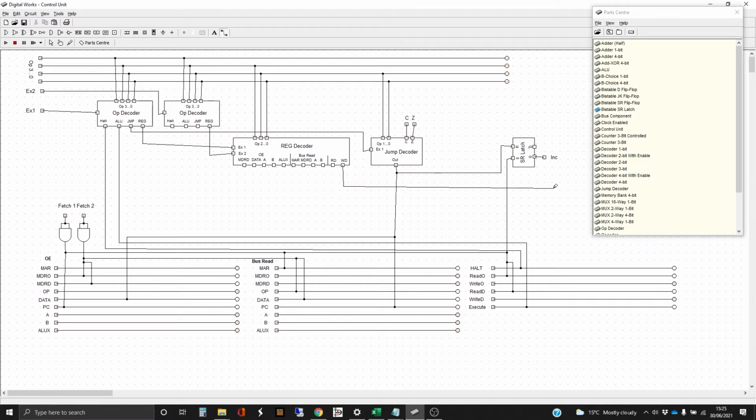So this is write data. Write D. This is read data. RD. Oh, sorry, RD. Unable to connect two outputs. So that already has an output from something, from there. So I'm going to tap into that and use an OR gate.